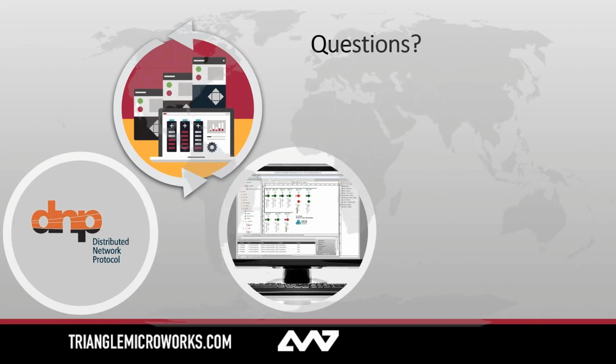And in case things are going too fast, there's too much going on at once, and you can't keep up with the output, there's also an error log button that you can click and it will bring up all sorts of errors, and then another tab is all the warnings. So you can go back and actually watch what happened when the error happened and figure out, oh, the very first thing that happened before all these error logs is I lost, say, my Ethernet cable or something, and that had a trickling effect of all my devices disconnecting or whatnot. So there are two ways that you can monitor that directly.